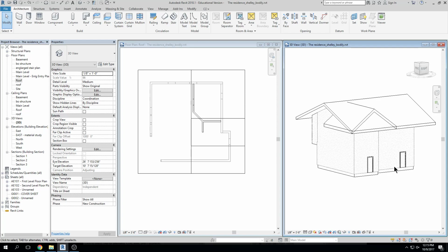Sorry, what were you trying to do? Oh, it's more okay. But now I'm trying to figure out why it's all raised up. It's because it's on the wrong level. So if you go to your east elevation, it's probably at your roof line and needs to be at top of the wall. So click on it and change it from roof to top of the wall. And then to change your overhang, you're going to hit edit footprint. You can't edit footprint in this view. And then